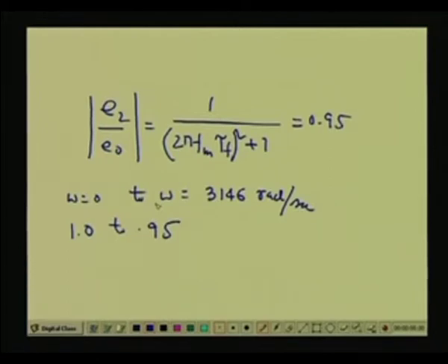Now, in order to determine the values of RF and CF, we use the fact that each stage in the process must have an impedance 10 times more than that of the previous stage. Now, you see the oscilloscope has an input impedance of 1 megohm, is not it. If the oscilloscope has an input impedance of 1 megohm, I can write 10 RF equal to 10 to the power 5 ohm. So, RF we can take equal to 10 to the power 4 ohm, right.